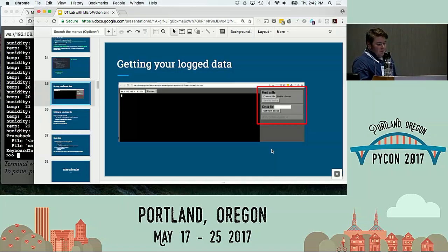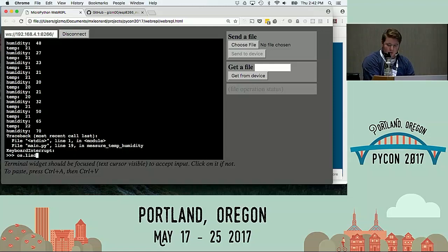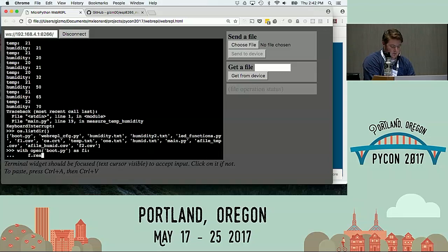All right. It looks like we're getting a coffee break at 3, and we were pretty much at the end of this part, the main.py file that I had mentioned. People have been asking, did the board just talk MicroPython or what did you have to do? Besides putting on the firmware, there's a few different files that MicroPython will read by default. One of them is boot.py. So if we go in os.listdir here, there's a boot.py function. If I just read this file and open it, with open, f.read lines,